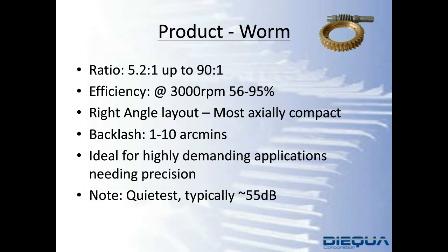A worm gearbox at 3,000 RPM is said to have high efficiency at near 95%, but at reduced speeds, the sliding elements of the worm gear induce a greater effect from friction. On low speed, high ratios, you'll see efficiency climb down to about 40%. So things to consider with low speeds: efficiency will go lower at higher ratios and at smaller sizes.